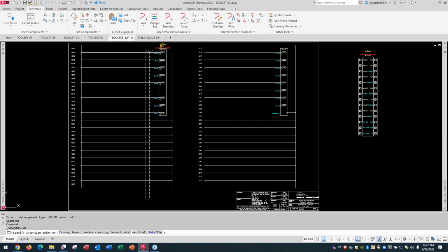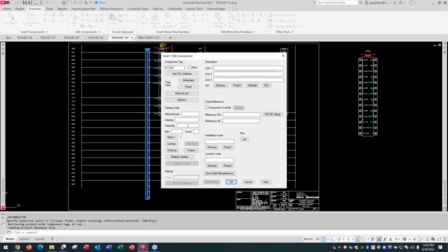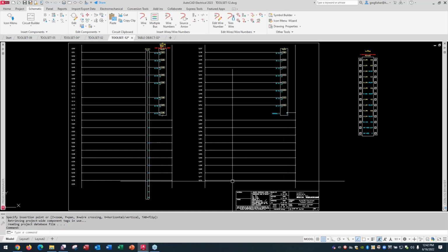Now I can drop the whole connector down and have it adjust to the spacing of the wire. And it's just another AutoCAD block with attributes at this point. And then I had it adjust to the spacing. So every single time it sees a wire, you put it in there. I didn't have to do that.